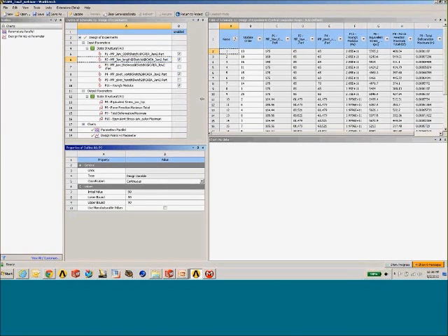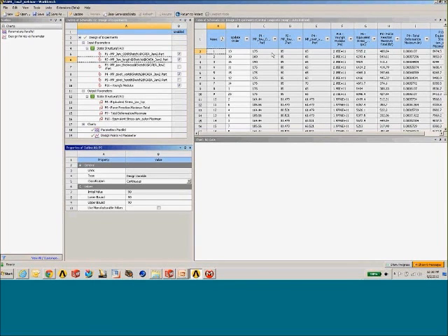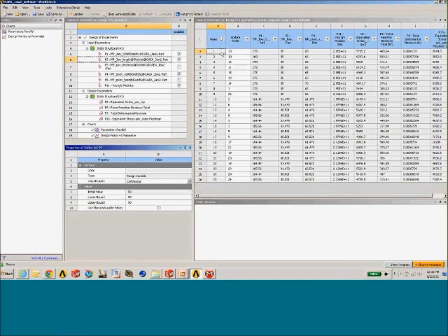We do the same thing where if we're using the remote solve manager, we kick off all these design points. Now, the reason we're doing that correlation, as I mentioned before, is the number of design points required in a DOE is directly dependent on the number of input parameters. So if you eliminate input parameters, you eliminate required design points. So that correlation step becomes a nice time saver for you in that regard. So we go back to our parameters that we're interested in. We specify their ranges. We generate the design point solutions.